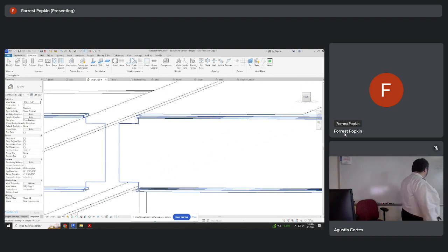if these two are at separate heights, and I'm putting something like a corrugated deck down, I'm only able to use either the horizontal or the vertical to attach to, because they're not at the same height. I'd want both these guys to be at the same plane in order for that to work. So my girder would want to be here at the same level as the top of the beams. Does that make sense?